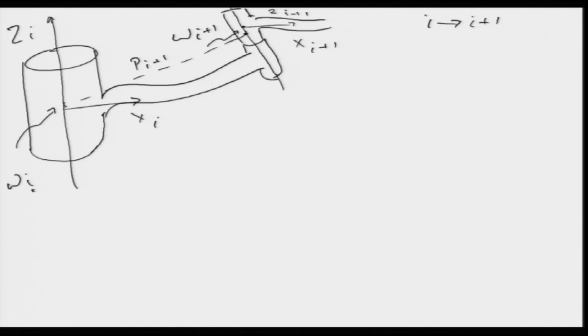So, we would like to find out that when the velocities are moving, how do they propagate from one link to another link. As you can see, this link has velocity omega i, this fellow has omega i, this one has omega i plus 1. So, when the velocities propagate, this link here will have the velocity of the previous link, plus its own velocity, i plus 1.